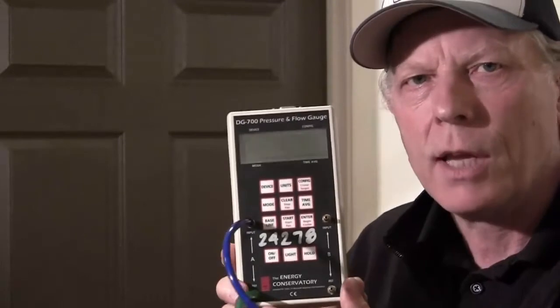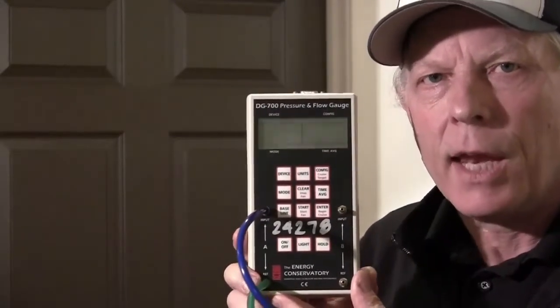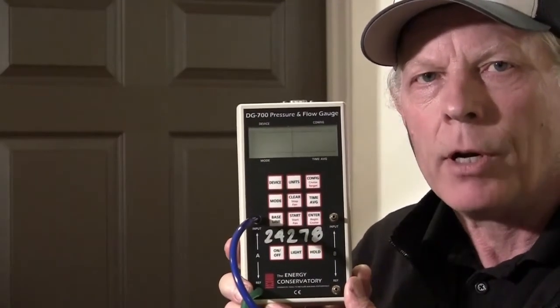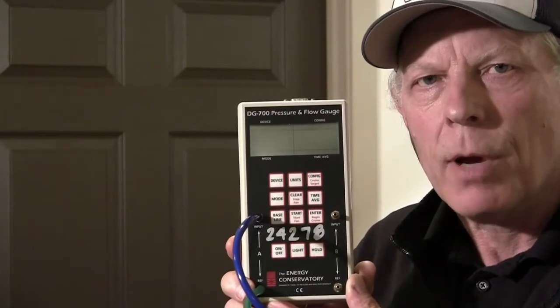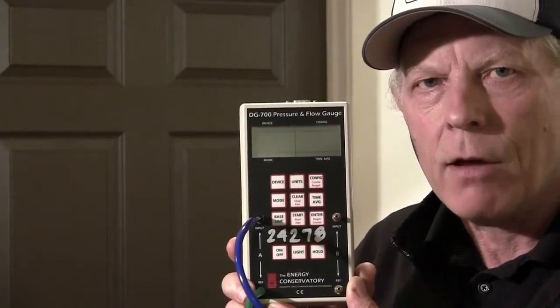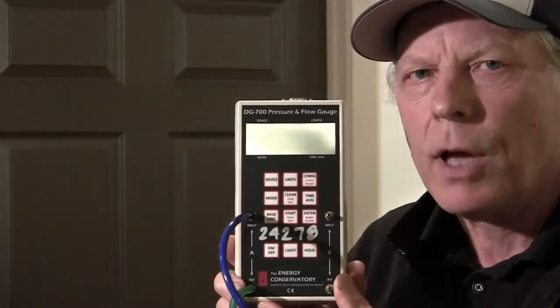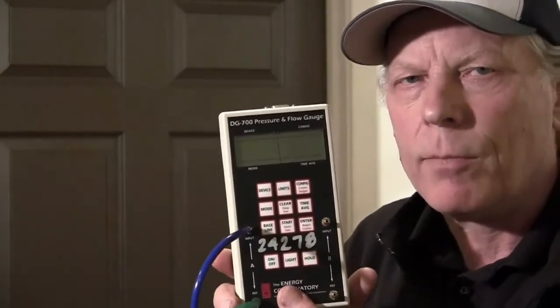and then we'll come back and set up the manometer on line 2. We're on line 2 of combustion appliance zone testing, and it asks the candidate to set up the manometer and the tubing for the manometer correctly. What I want to read is combustion appliance zone with reference to outside. Right now I am not in the combustion appliance zone, I'm standing outside of it.